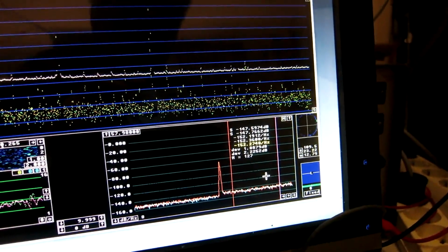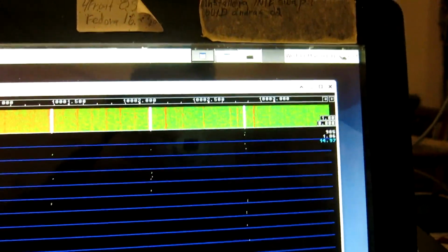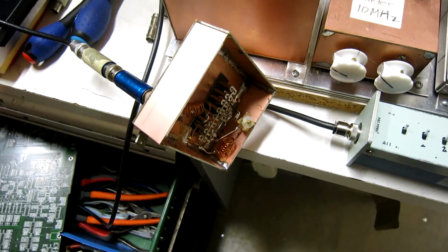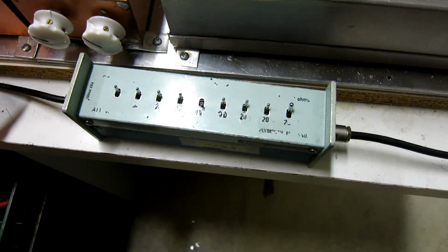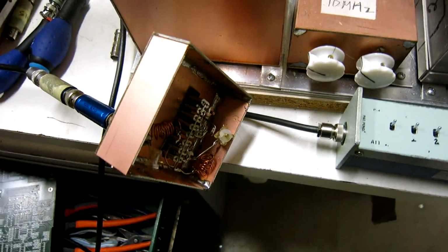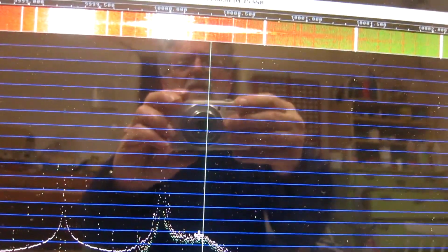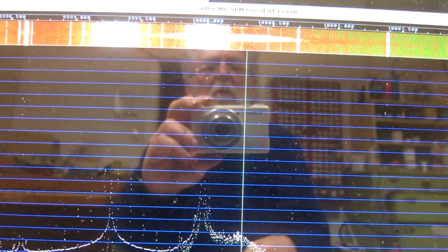It's minus 162, and the correlation advantage is 1.8, almost 0. I have moved the notch now to the other side of this 10 dB attenuator, so now it has 10 dB more power. And then this is what I have seen. There was an event here of high noise, a noise burst.